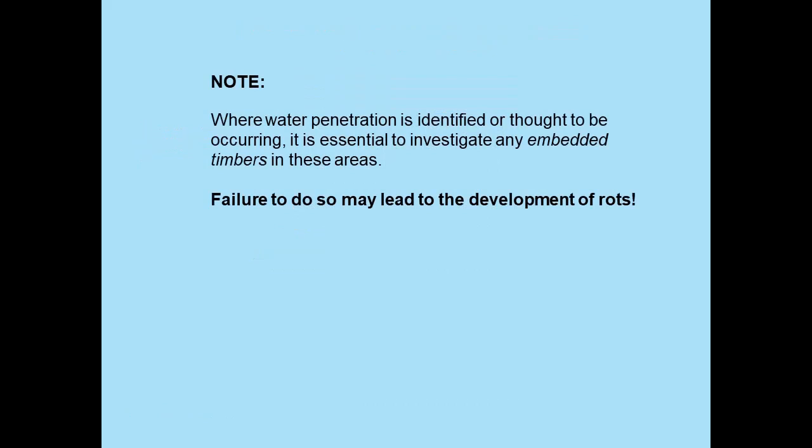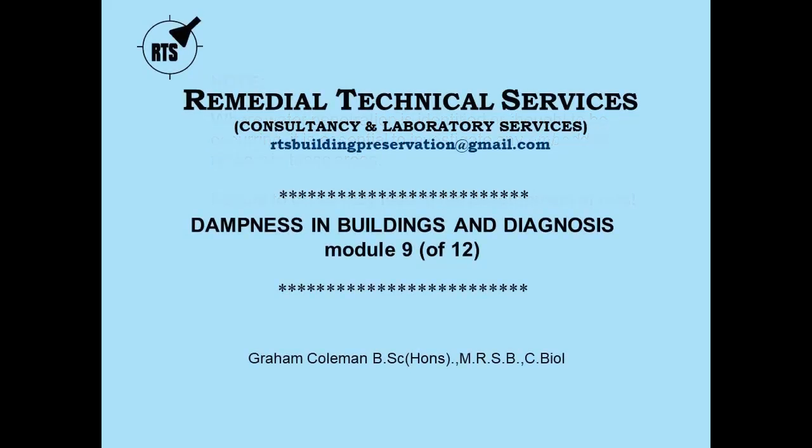Note, where water penetration is identified, or indeed thought to be occurring, it is really essential to investigate any embedded timbers in these areas. Why? Failure to do so may lead to the development of rots. If it stays wet long enough, it will rot, but the timbers in such areas will always be at risk to rot.